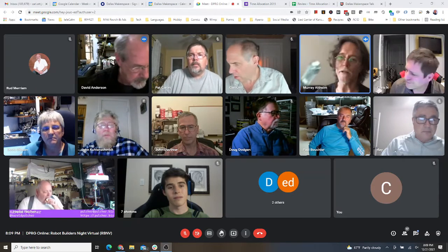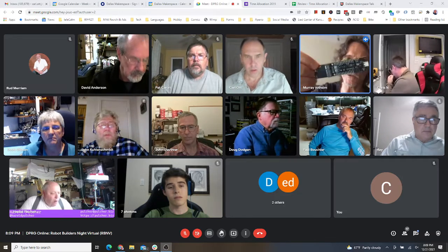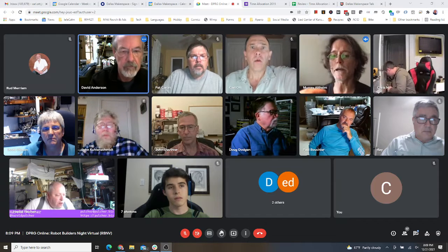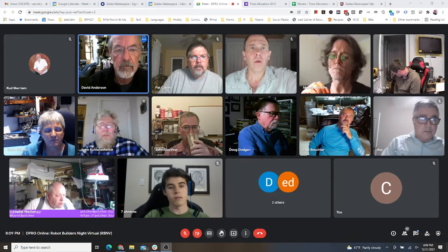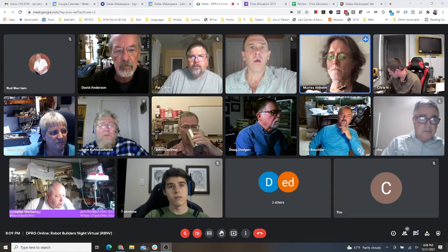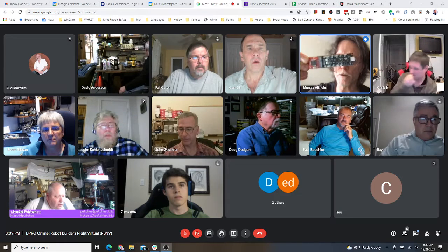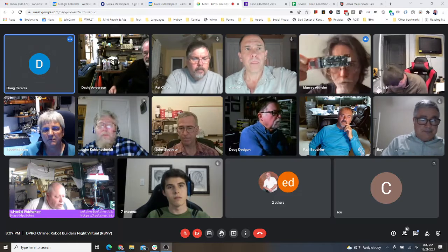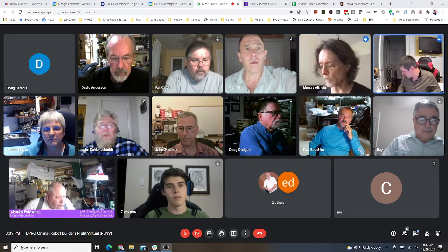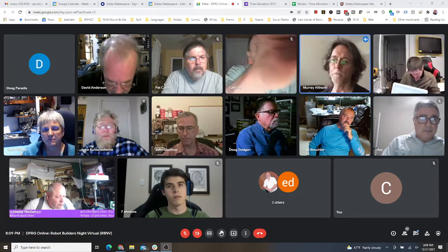For example, here's the Feather board. This fits onto the Feather in the same way, so you end up with a Feather. Now, the one thing I will confirm is that I think it's the UF2 bootloader. The bootloader that's currently on the board boots as a USB device.